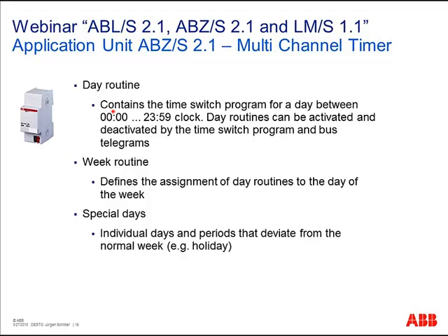A day routine will be assigned to a week routine, meaning the 7 days in the week have different day routines. So maybe working days from Monday to Friday are the same, but during the weekend you might have a different time function. Again, special days, holidays for example, can be created with totally different time functions.